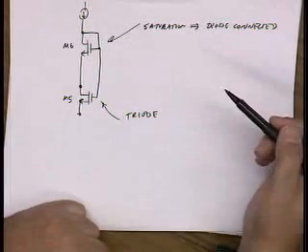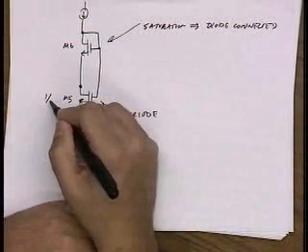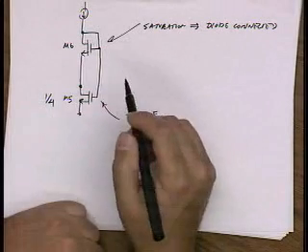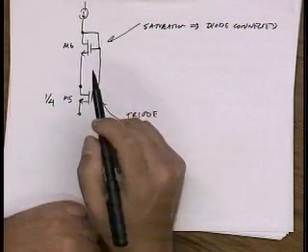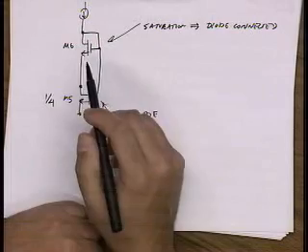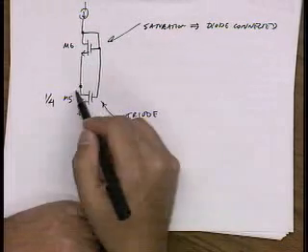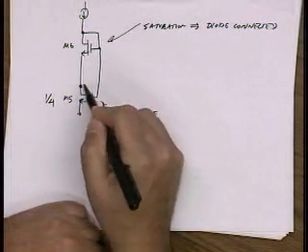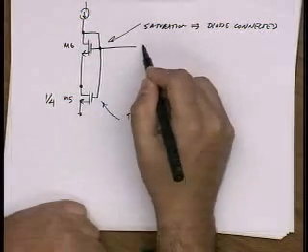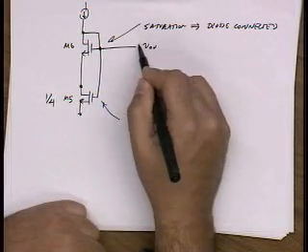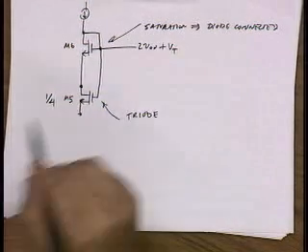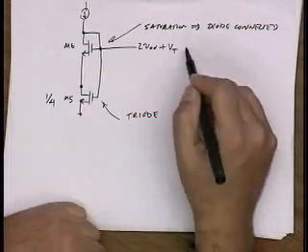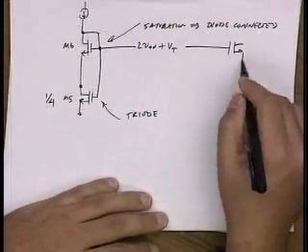Okay? And so if you go through the equations, I won't bother here, if I make this a 1/4 device, then you can show that the overdrive voltage of this device is exactly the voltage you need to bias. Basically, you get one overdrive here. So at this point, you get 2 overdrive plus a threshold voltage. So this is exactly the reference I need to bias up my transistor. So I'll go ahead and connect this to my cascode device.